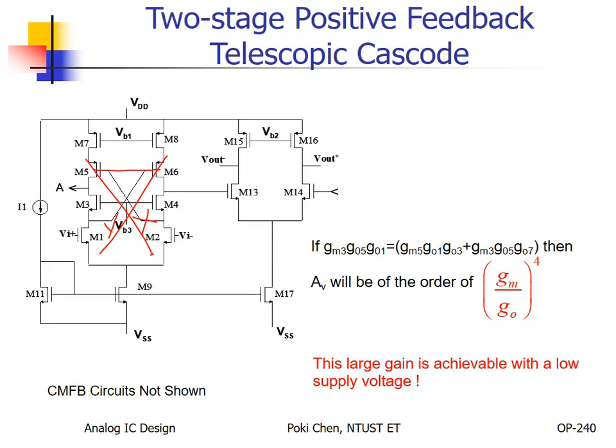During design, usually you will face some transistor being pushed into triode region or cut off. So the major challenge is to make everybody operate in saturation region. Easy to say, easy to talk, but really hard to implement. Anyway, the concept is quite easy, from this connection to that, to get some kind of negative impedance or positive feedback.